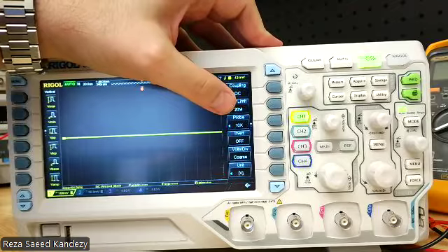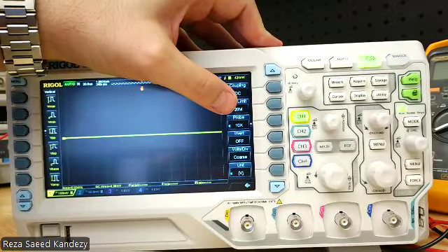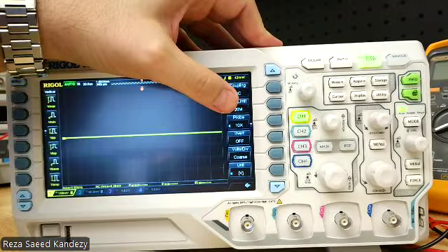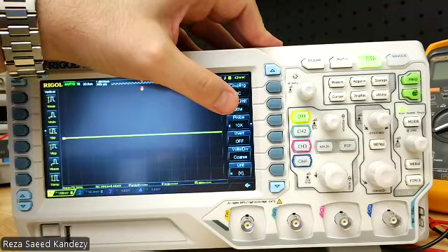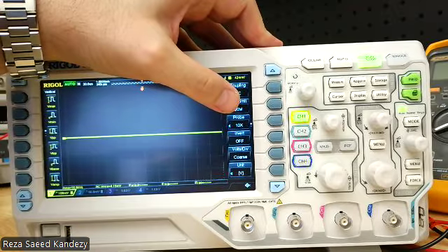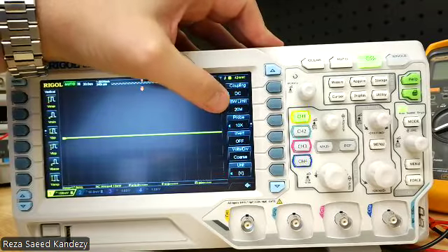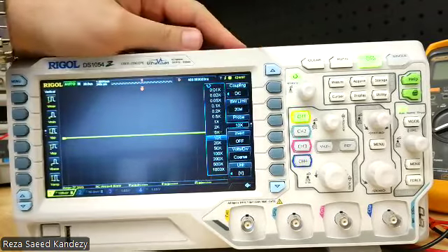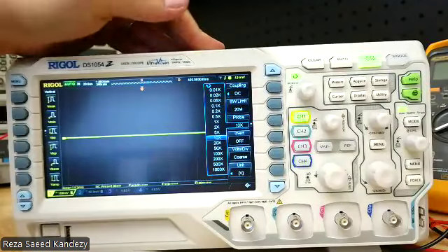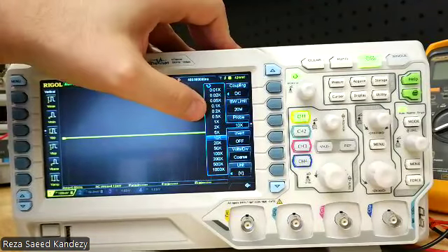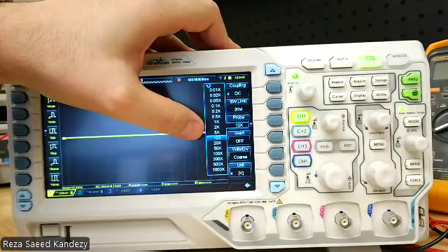The probes that we are going to use for injecting the input and measuring our parameters have a certain amplification, so certain coefficients. You have to define the coefficients here. If you click on that menu, you see you have several options. We normally use either ×1 or ×10 because of the probes that we use in the lab.